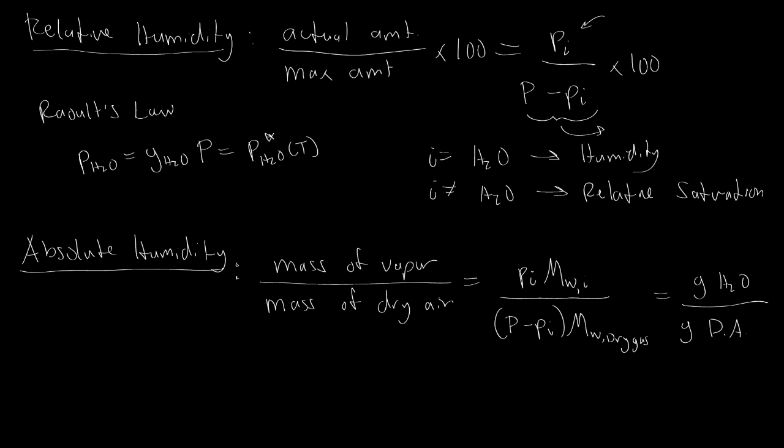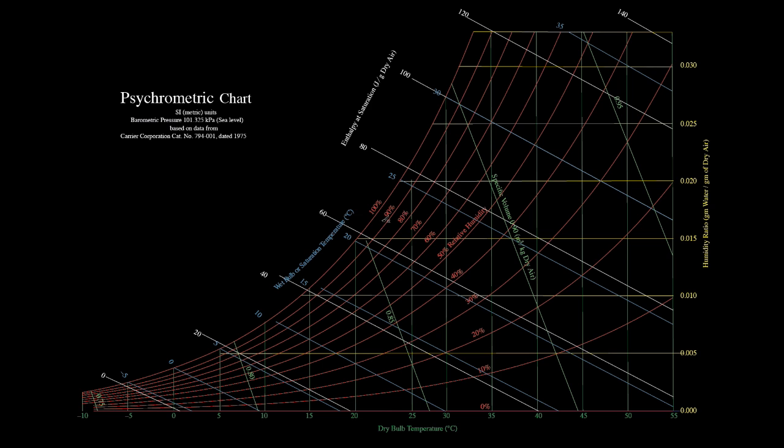One very useful tool for doing humidity-based calculations, which can ultimately be tedious oftentimes, is to apply a psychrometric chart. Now, a psychrometric chart is a very common engineering chart that has a lot of information, and so I want to do a quick breakdown of the key features of it so that no one is concerned about it. I'll switch to probably a pink here for color so that it can be easily distinguished from the cornucopia of colors we have already. On the x-axis, we have what we call the dry bulb temperature, and this is effectively just the normal temperature, what we would see on a thermometer or something.